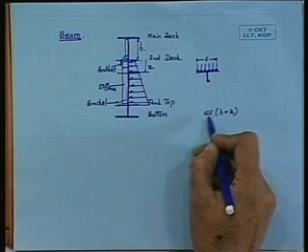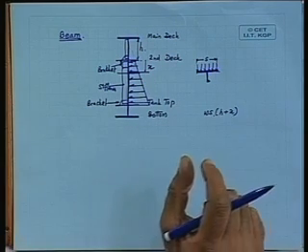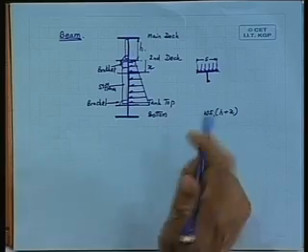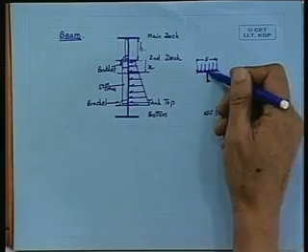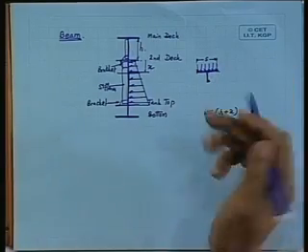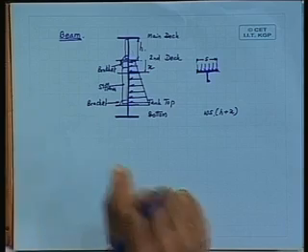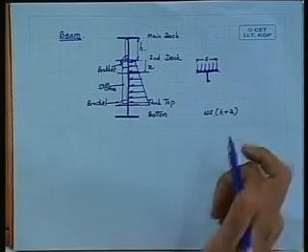So, basically multiplying by that frame spacing gives me the intensity of loading at that particular position of the bulkhead plate and stiffener combination. Okay.